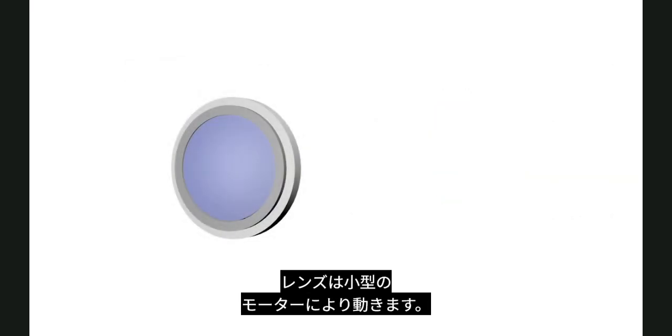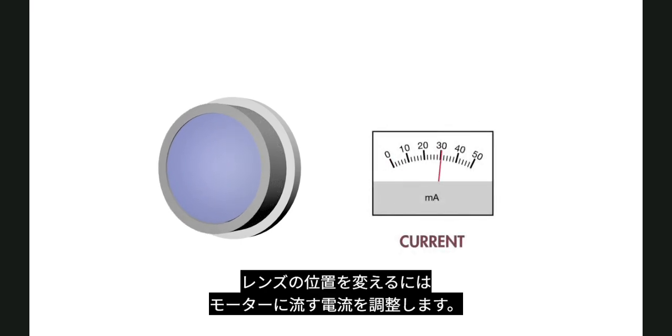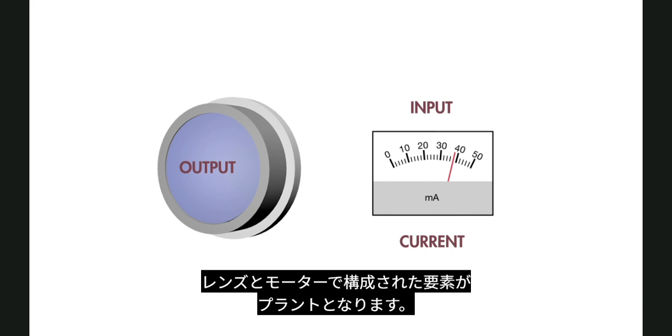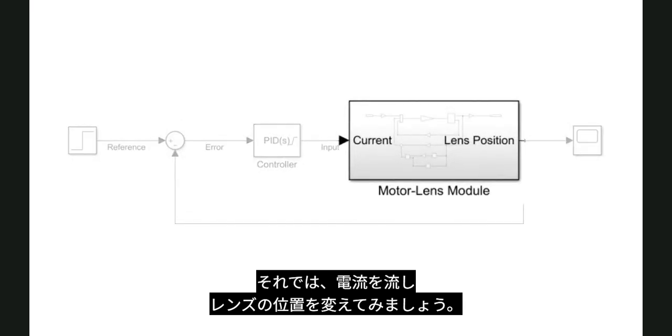The lens is driven by a small-sized motor. We can change the lens position by adjusting the current applied to the motor. Here, the current signal is the input. The position of the lens is the output, making the lens motor component our plant. Now, let's change the lens position by sending in some current signals.